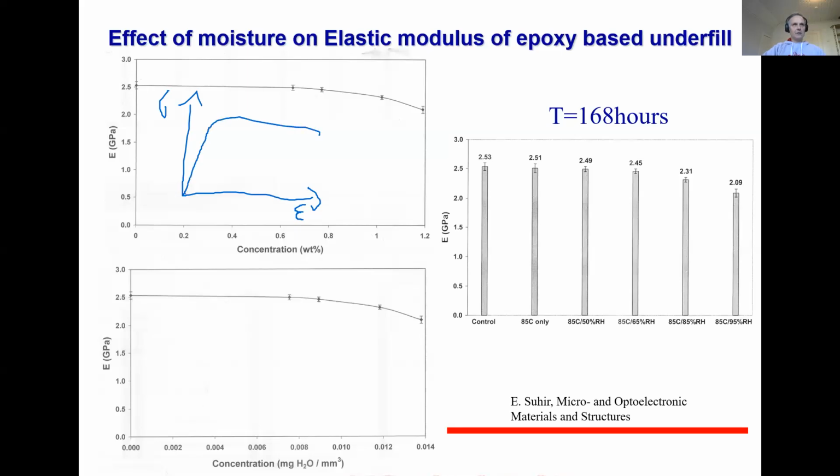For polymers, it could be something like this. But anyway, here we have the yield strength, which means that up to here, when we increase the displacement, everything is recoverable. If we put stress, the displacement increases up to here, but if we release the stress, then the material comes back to the original position. So this area is elastic.